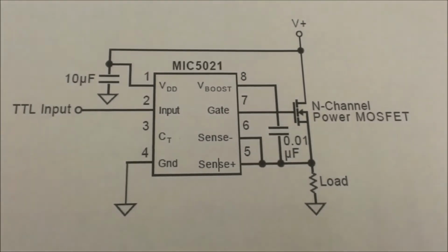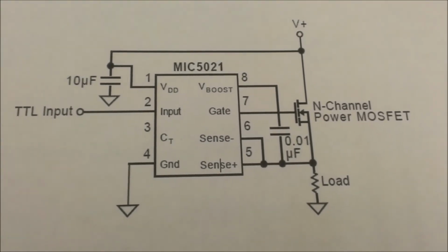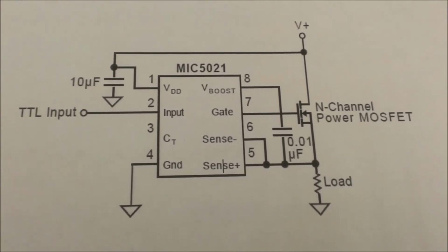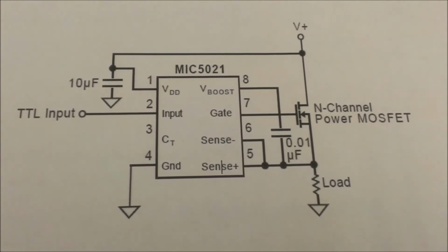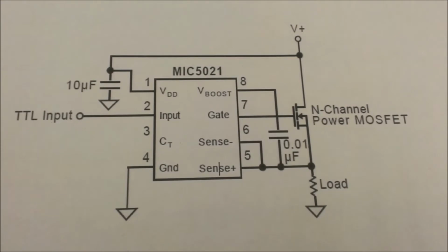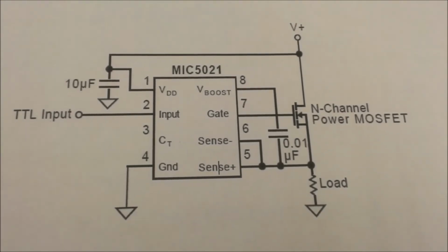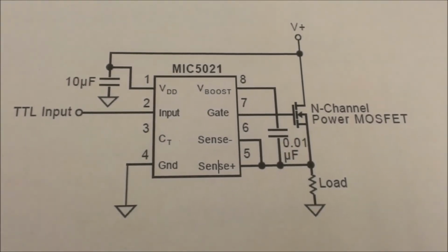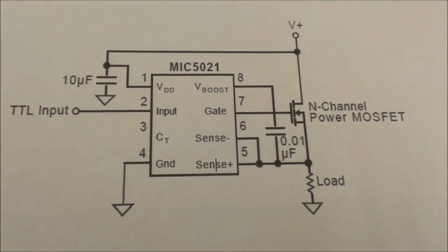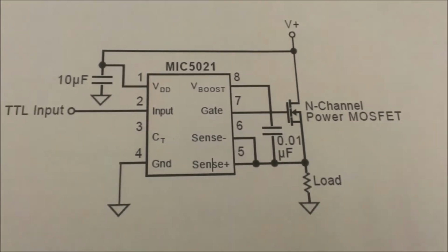This is the high side gate driver with the high side switch diagram. As you can note, there is only one power supply being used and all the grounds are the same, unlike the previous circuit with the low side driver and high side switch, where that used 2 power supplies and it had separate grounds. I would also like to note that there are different capacitors within this circuit, and that is based on the different kinds of high side gate drivers. I would like to show the circuit now.